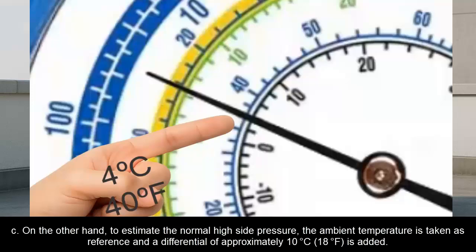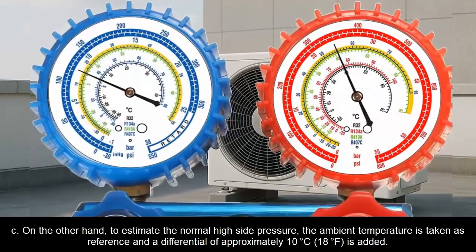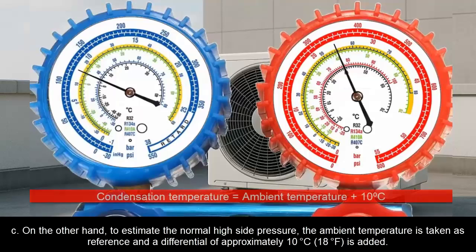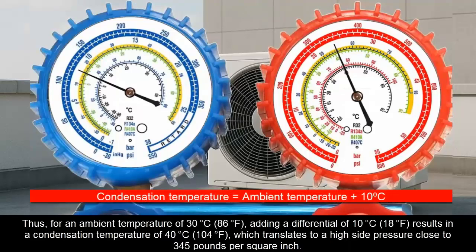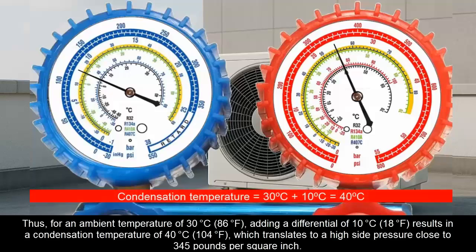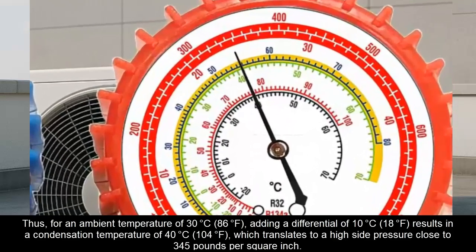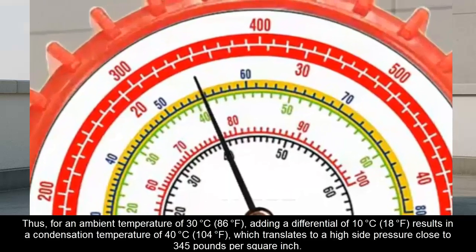C. On the other hand, to estimate the normal high side pressure, the ambient temperature is taken as reference and a differential of approximately 10 degrees Celsius, 18 degrees Fahrenheit, is added. Thus, for an ambient temperature of 30 degrees Celsius, 86 degrees Fahrenheit, adding a differential of 10 degrees Celsius, 18 degrees Fahrenheit, results in a condensation temperature of 40 degrees Celsius, 104 degrees Fahrenheit, which translates to a high side pressure close to 345 pounds per square inch.